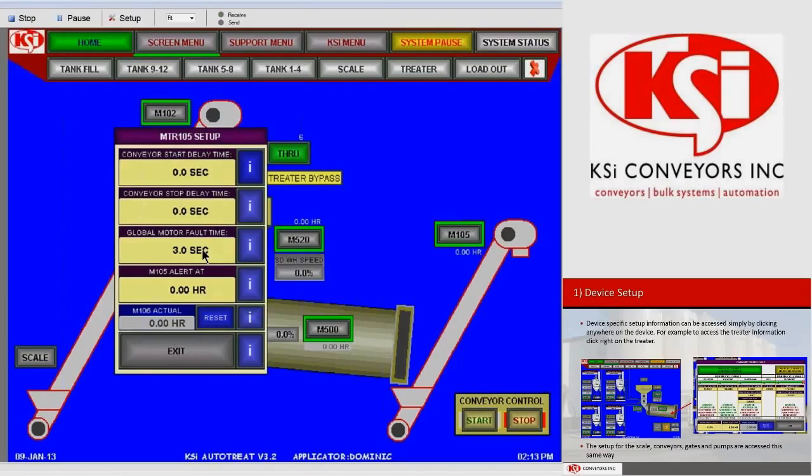This is a safety measure added to all automation systems to protect the system from putting seed or material where it's not able to be conveyed from. For example, if a motor doesn't turn on, we don't want the system to provide seed to that location, as that will cause system stoppages or cause seed to spill or something to that nature.